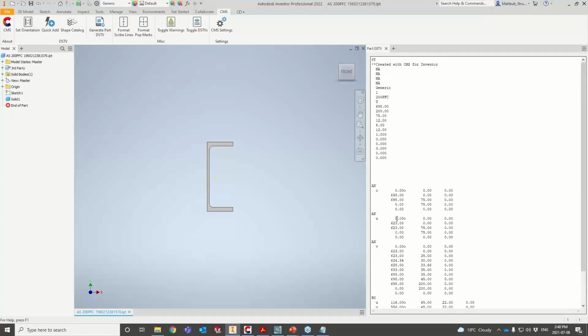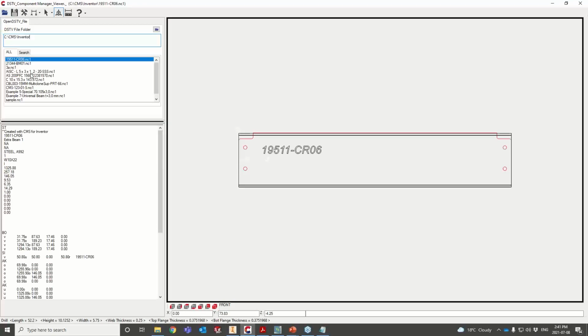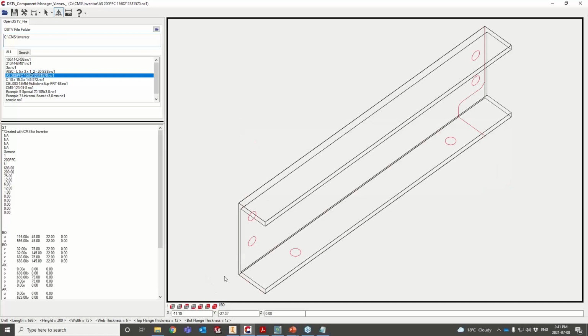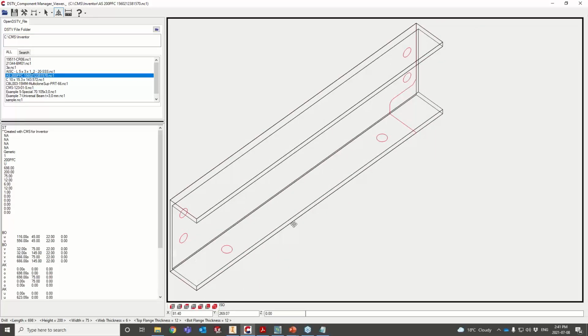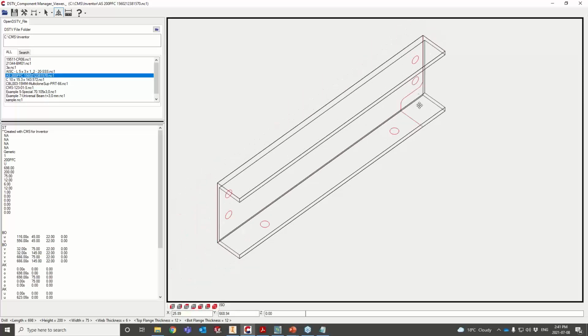Okay, so if I just want to see the NC1 file that just been created, I'm just going to refresh that. It's always better to verify your NC1 file every time you create it. So your best bet would be to process all the NC1 files first, and then come to the viewer and verify each and every one, right? As you see, I was able to capture all those cuts and the drills with no issue at all. Okay, so it's very smooth operations here.